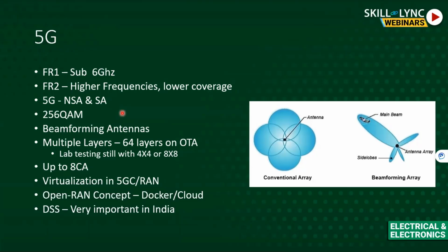Because FR1 alone with 100 megahertz, we are already testing about 1.8 Gbps. Okay. That's where we pointed out saying, if you go back to the first slide, we mentioned that in 5G, we are looking at greater than 10 Gbps. In FR1, a single cell can do up to 1.8 Gbps. And in FR2, a single cell can do up to 7.5 Gbps, right?